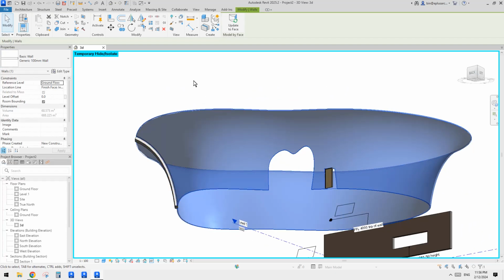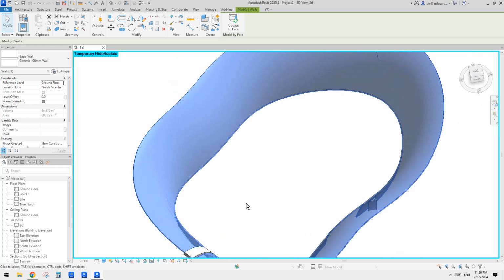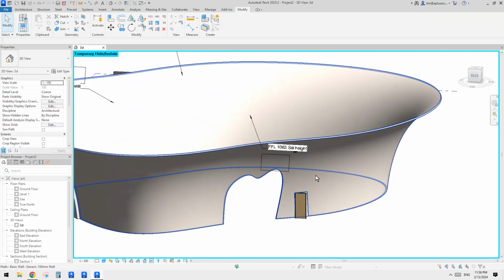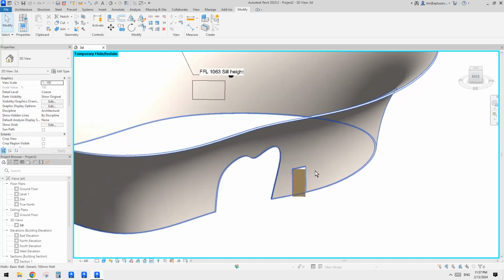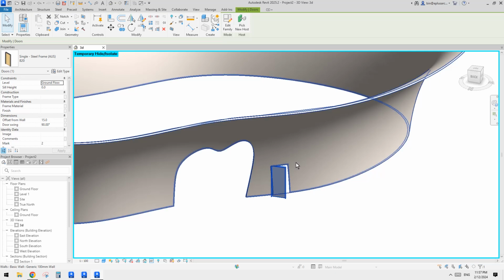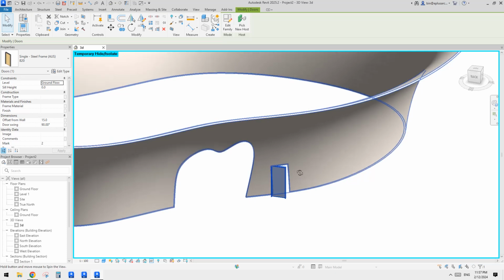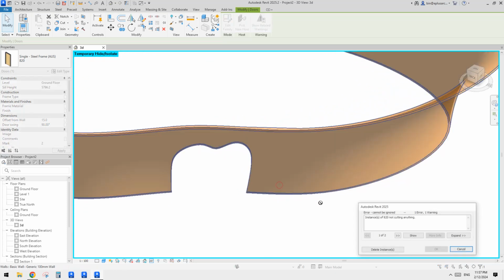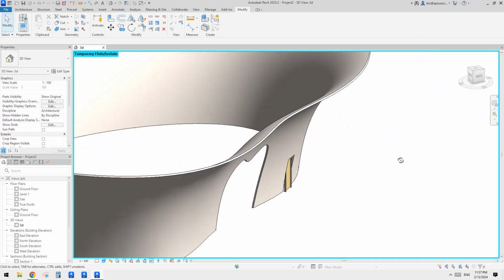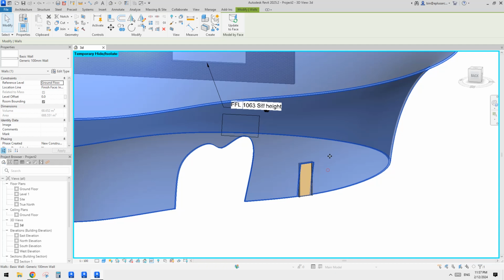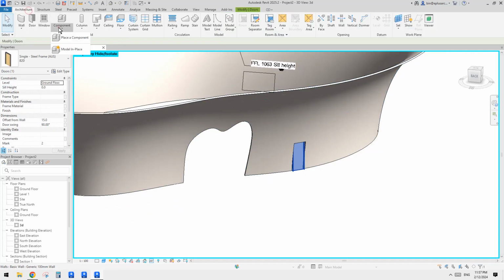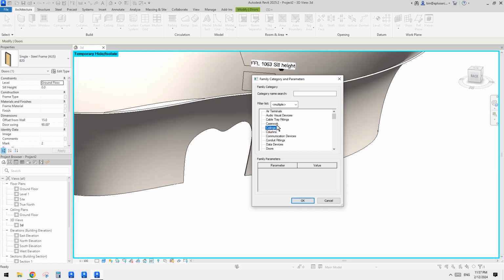Maybe 100 wall. Yep, good. Okay, and we also have a different option to create this opening. We can just directly create a model in place void. What's going on with? Oh, not sure. Looks like every time we update the wall, we need to update the door as well. So we can also use model in place.